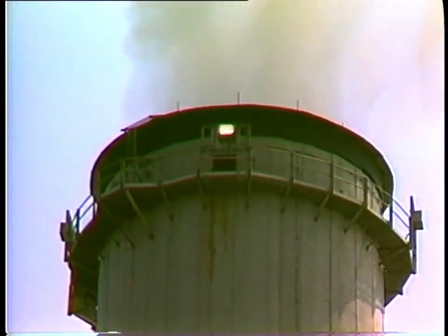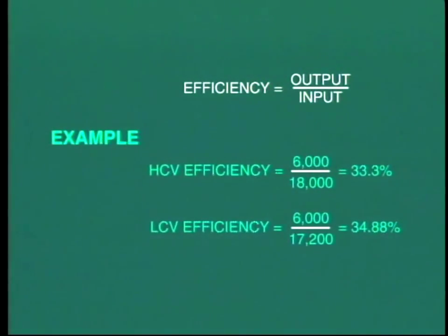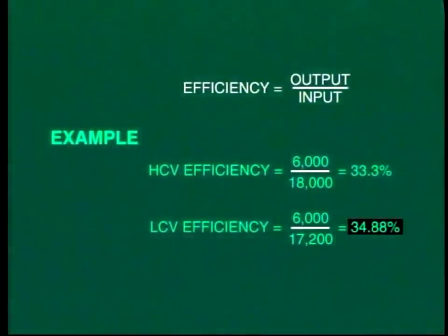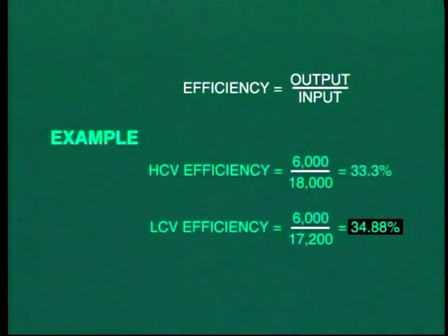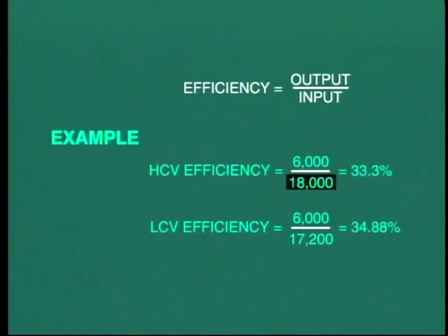However, beware, in many other situations, for example, in many European plants and European manufactured equipment, the quoted efficiency is based on the lower calorific value. This would, of course, provide an apparent higher number for efficiency. Clearly, if the heat input to the plant is indicated at a higher value, then the calculated efficiency would come to a lower number. Now, I'm sure you're pleased to know that it's time for a break.